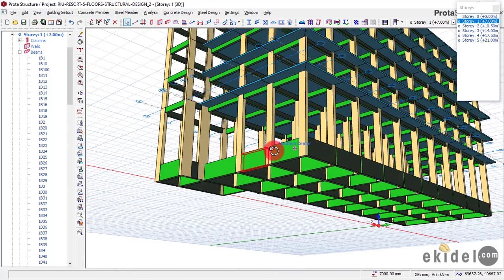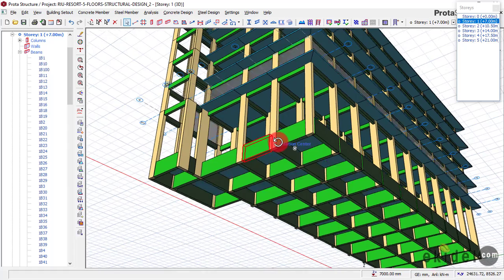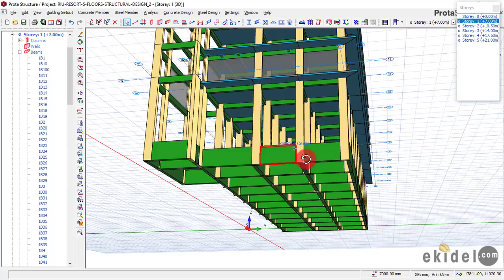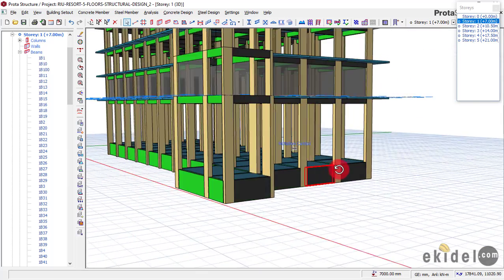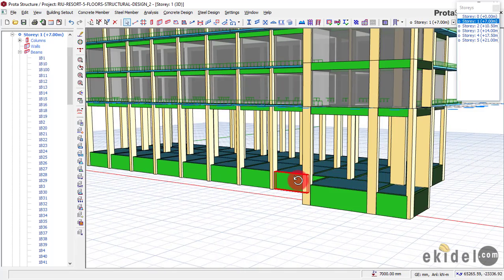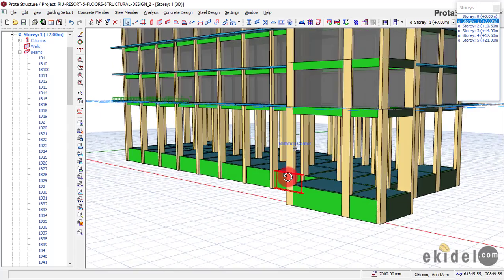If you check below, you will see that there is a void which will be filled up with sharp sand, very well compacted, although you will learn that more at the construction stage. Okay, so right now we are done with this part 2, which is the modeling stage of your Raft foundation.